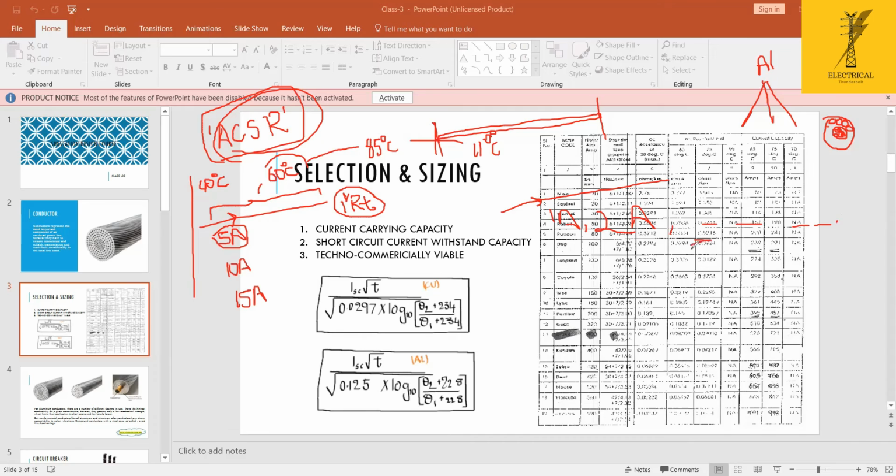But when it reaches 5 amps, I noticed that the conductor broke down and was damaged. Because when I inject 5 amps, the conductor temperature rises to 120 degrees Celsius, and the material cannot withstand that. So my conductor broke down. Then I will say that the selected conductor can carry a current of 4 amps only.